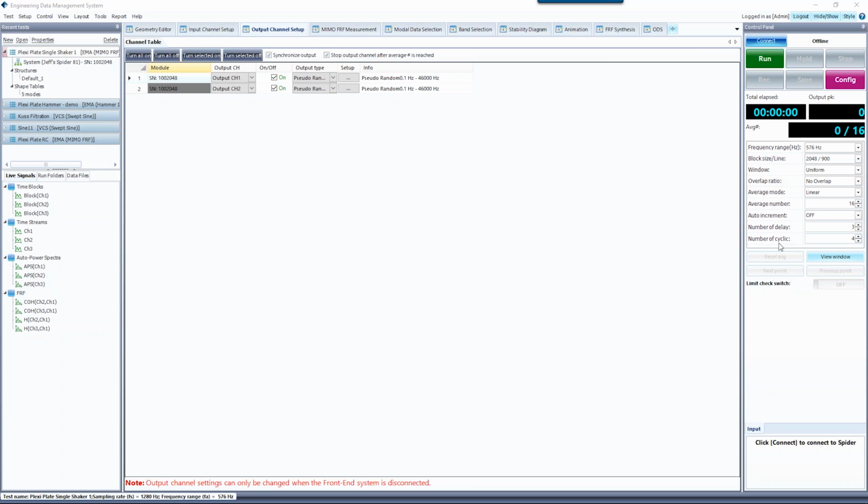So you tune the burst random percentage to allow time for the response to decay, very similar to the hammer impact test. You can tune the block size to have the response decay to 0. If this is achieved, you can just use the uniform window. You don't need to use the Hanning window. That's why burst random is very popular for people doing modal shaker testing.